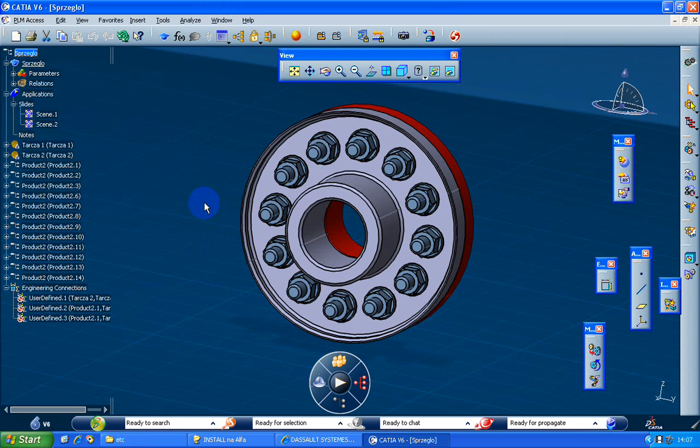But I will continue with versioning because we are still talking about lifecycle operations. And versioning, of course, means you can create a new version of the product. For me, when you create a new version of the product, from version A you create version B, it is called versioning. It is something like creating a new flow in CATIA V5. You create a new object, which means you will also change the ID. You keep only the relationships and attributes, meaning you keep the form and the shape, but not the maturity status.